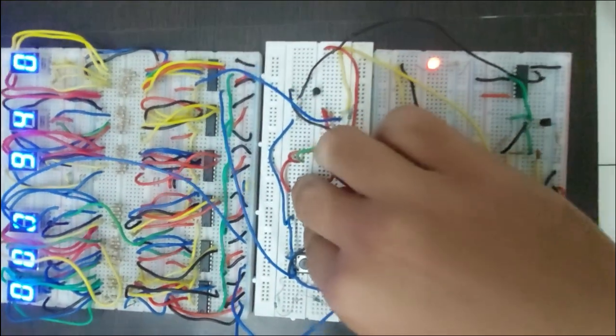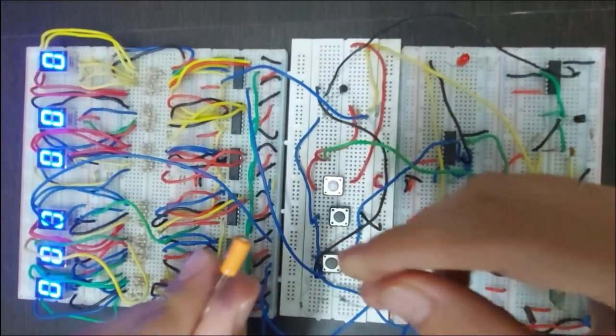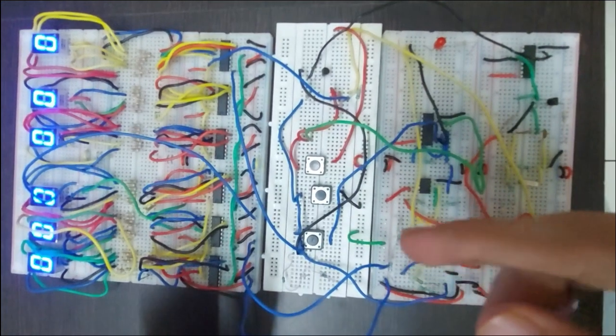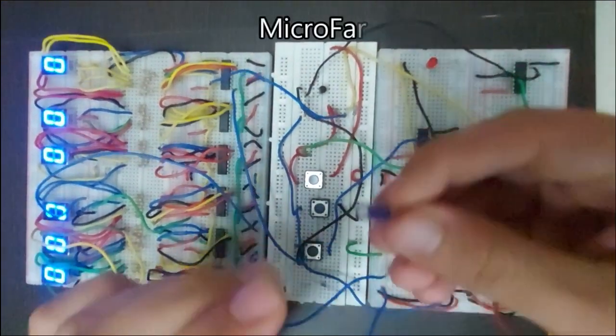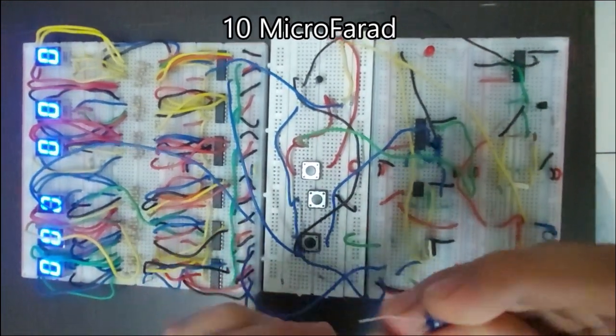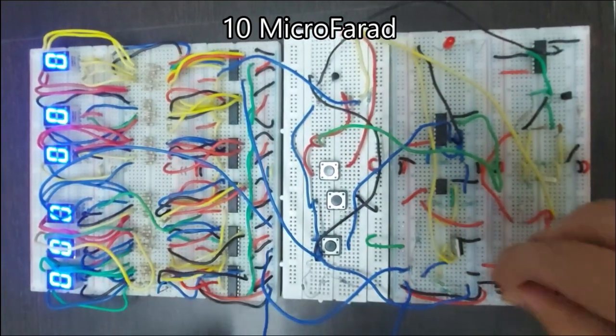We are going to reset the circuit. So for 1 microfarad, the circuit shows 0.947 microfarad. We are going to test the 10 microfarad capacitor. Again we have to mind the negative and positive leg of the capacitor.